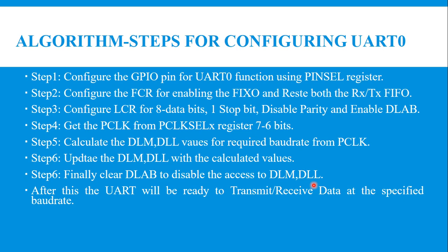Otherwise, if the baud rate is changed, whatever character you type on the keyboard might not be received properly. So these are the six steps we need to configure. After this, your UART will be ready to transmit or receive data at the specified baud rate.